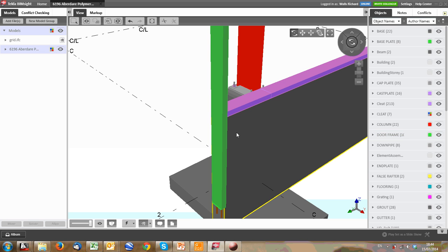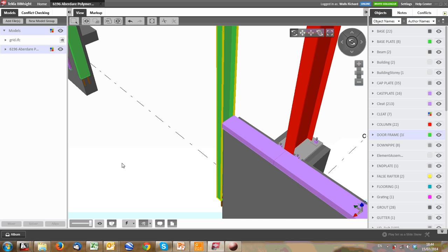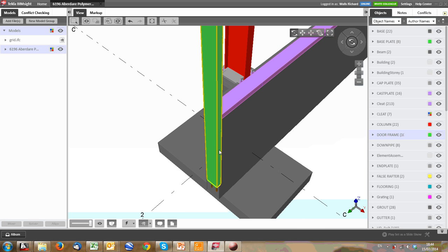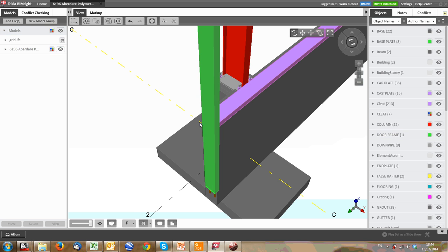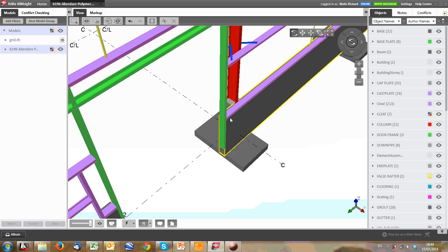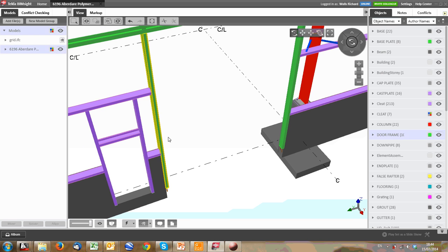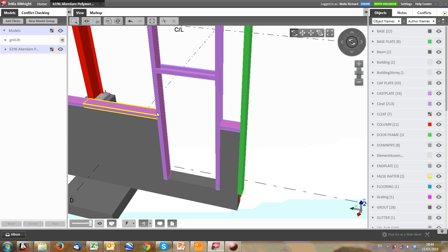Otherwise you move it backwards and tie it in with the brickwork, this PFC, parallel flange channel steel, and then if it's back from the girt, you need to make sure there's a little angle or something in the front that you can fix steelwork to. If you've got doors, you can do it with cold formed lip channels.